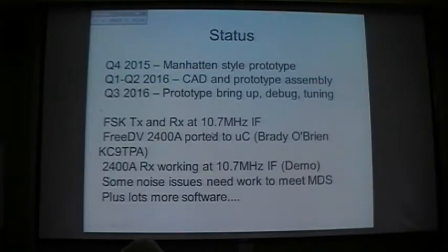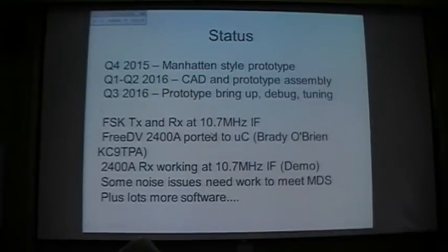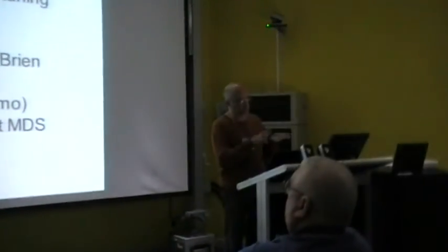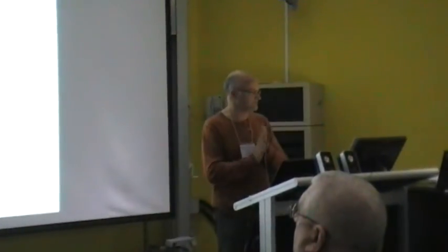And then over the last probably 3 or 4 weeks, Brady and I have been bringing up the first prototype at the bench at my house and having a bit of fun with that. And that involves soldering bits together, putting code on the microcontroller. We hook the USB port up to our computers and we can upload chunks of data and have a look at the signals that are going into the thing. So a lot of it's based on the laptop. Write a lot of code on the laptop, download it, flash it.